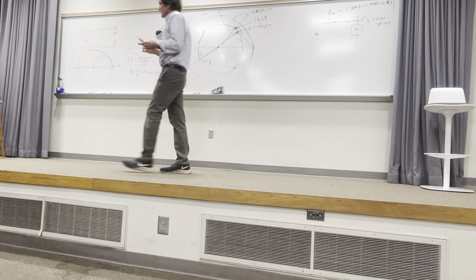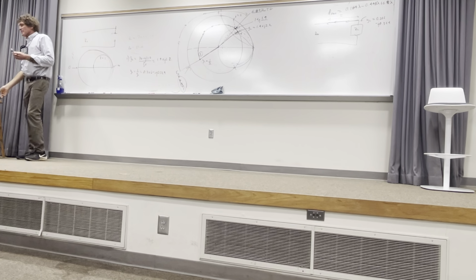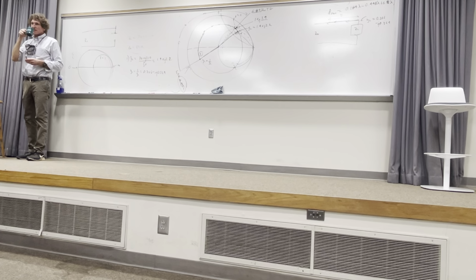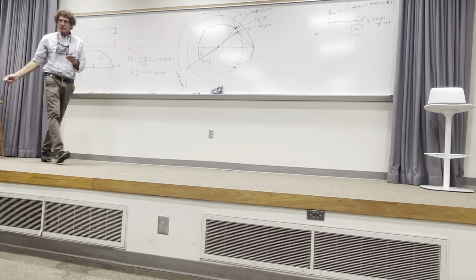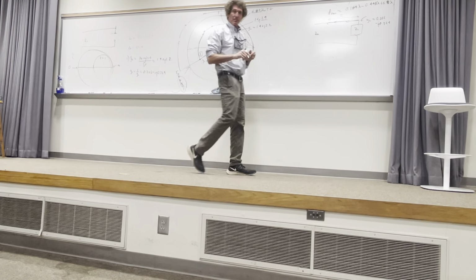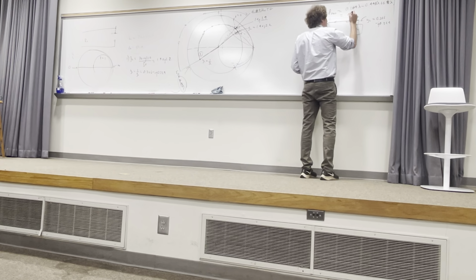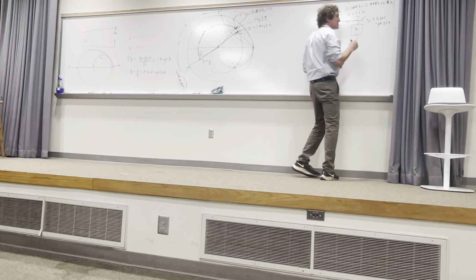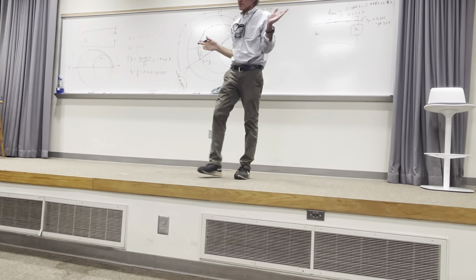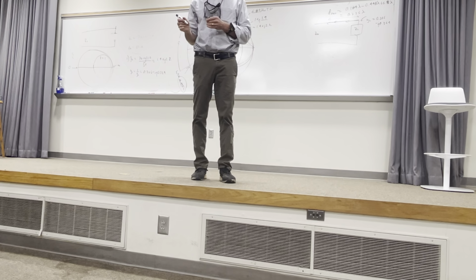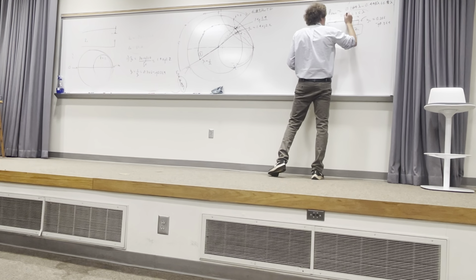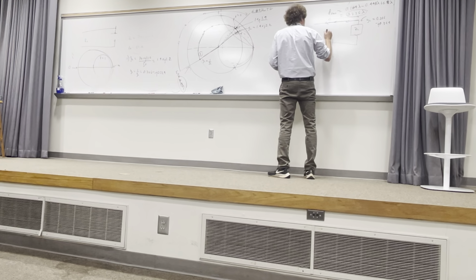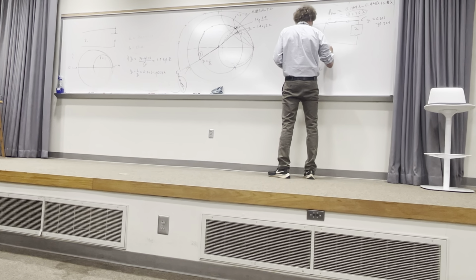I hope I'm being clear. Sometimes there are very small subtleties. 0.236? 0.236, guys? Is that right? All right, so it's 0.236 lambda. That's just shy of a quarter wavelength. 0.25 would be a quarter, right? All right, that means we've got this distance here. Here's where we're going to connect our open circuit stub. Now we need the stub length.